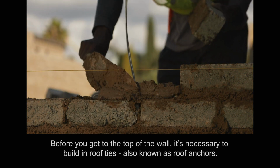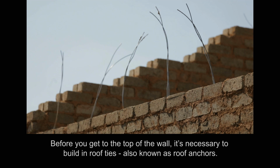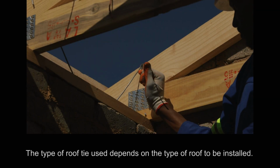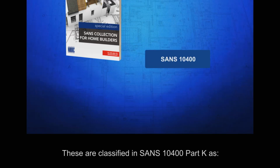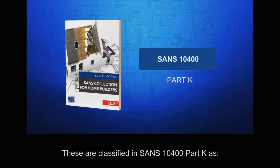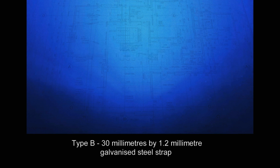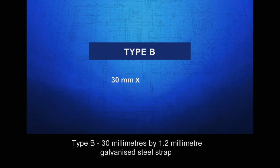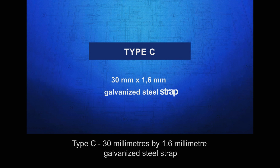Before you get to the top of the wall, it's necessary to build in roof ties, also known as roof anchors. The type of roof tie used depends on the type of roof to be installed. These are classified in SANS 10400 Part K as Type A, 2 strands of 2.4 mm diameter galvanized steel wire. Type B, 30 mm by 1.2 mm galvanized steel strap. Type C, 30 mm by 1.6 mm galvanized steel strap.